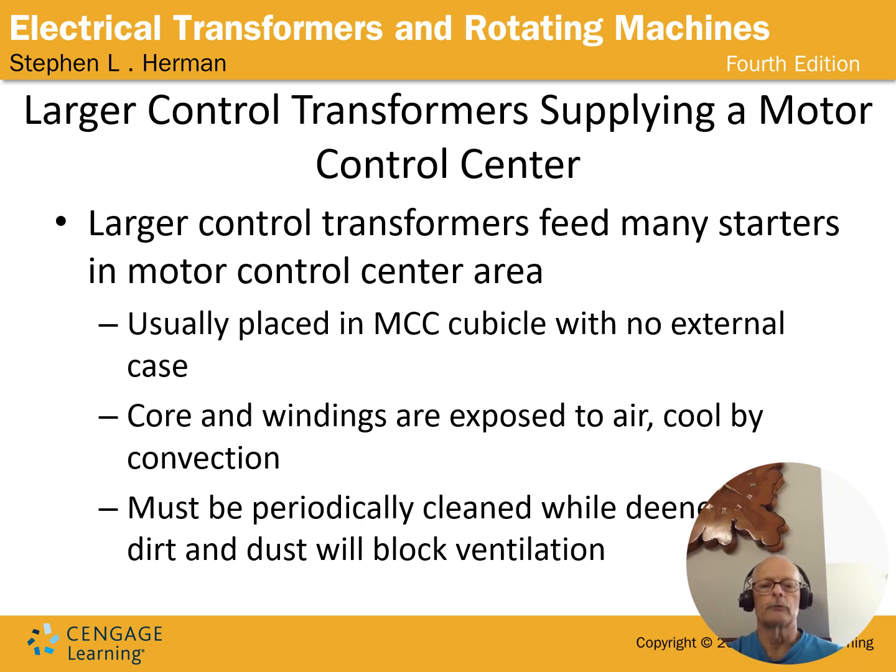Notice it says right here that they must be periodically cleaned while de-energized to get rid of the dirt and the dust that block ventilation. If that stuff's in the way, or if you have a filter that's not been changed and air can't flow, the ventilation is not going to work. The air cooling is not going to work.